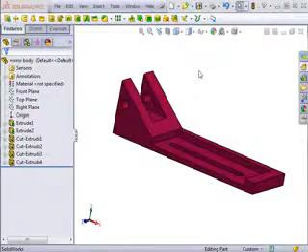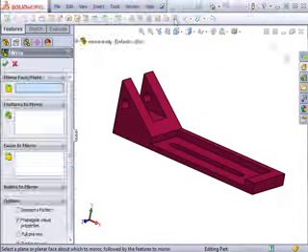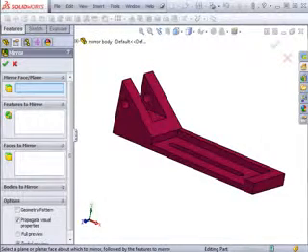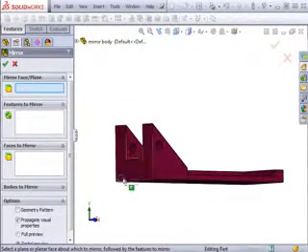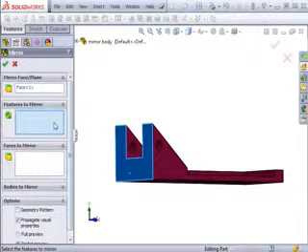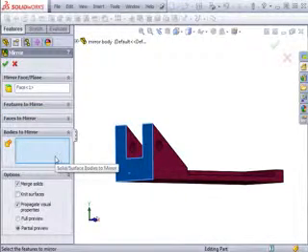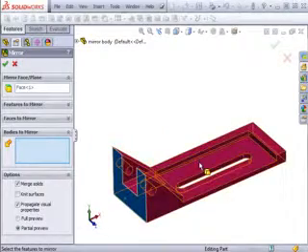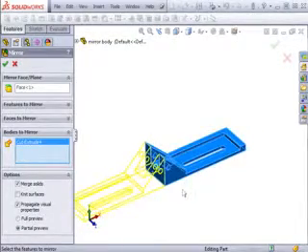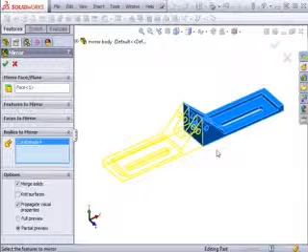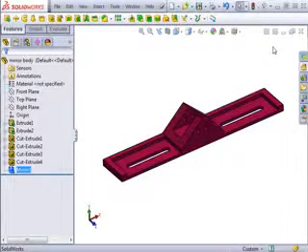If the part you are modeling is completely symmetric, you can save even more time by modeling half of it and replicating the entire thing rather than individual features. The same mirror feature is used to accomplish this. Instead of selecting a plane as my reference, I'll select this face. Since I'm not going to mirror individual features, I won't select anything in this window. Instead, I'll use the Bodies to Mirror window and pick any face of the model. Again, you'll see a preview of the geometry that will be replicated, and the green check will finish this feature.